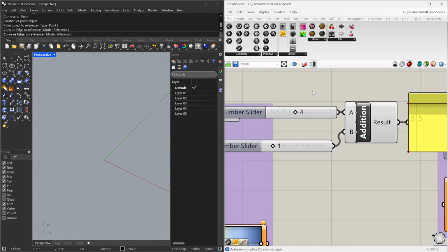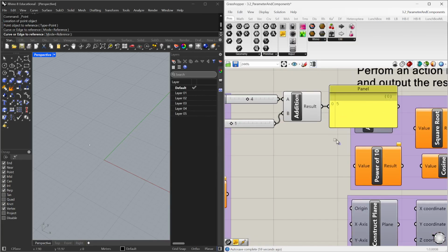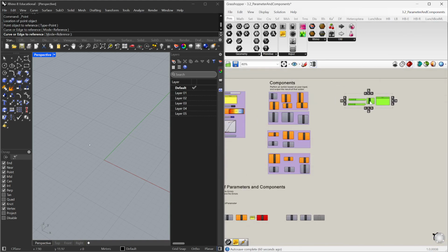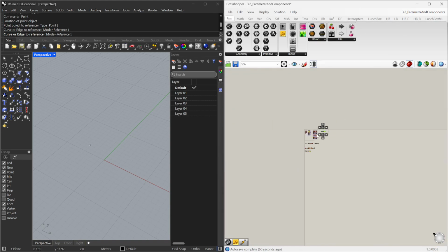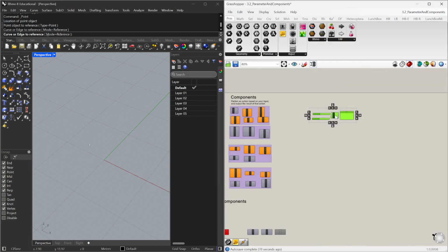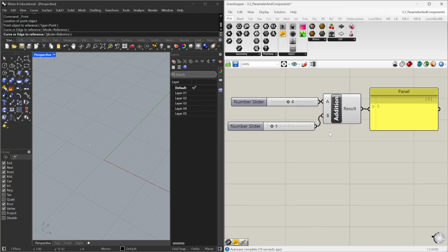If I wanted to adjust this number slider, I'm just going to bring this across. The other thing I can do is select any of my nodes and drag them across in this canvas. And this canvas is huge. I can scroll out and scroll in, and I can move this to anywhere on this canvas. Now you can see the different input and output data that I have.